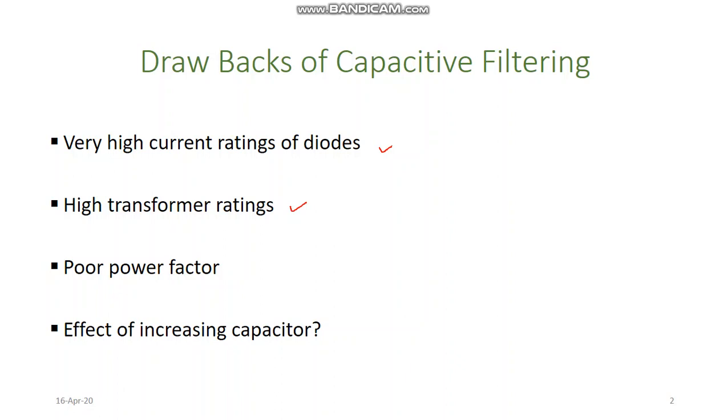But in this case, the power factor is low, but it is not due to an inductive load, as in the case of industrial loads. It is due to the conduction time of the diode, which is very short when a capacitor is used at the output as a filter.